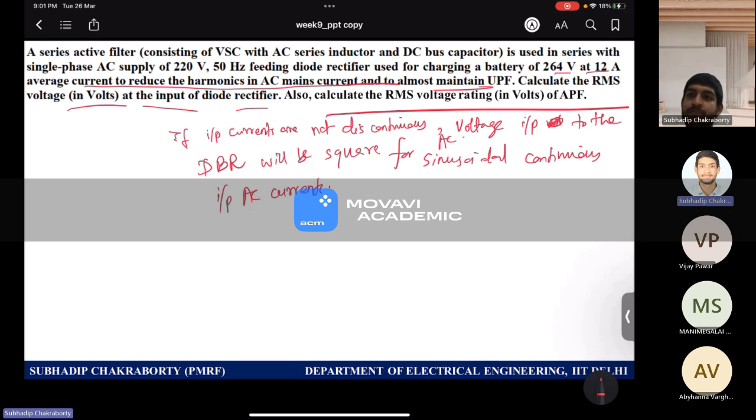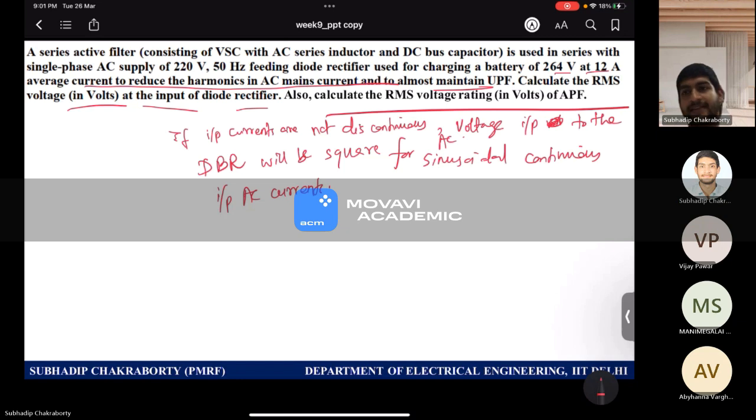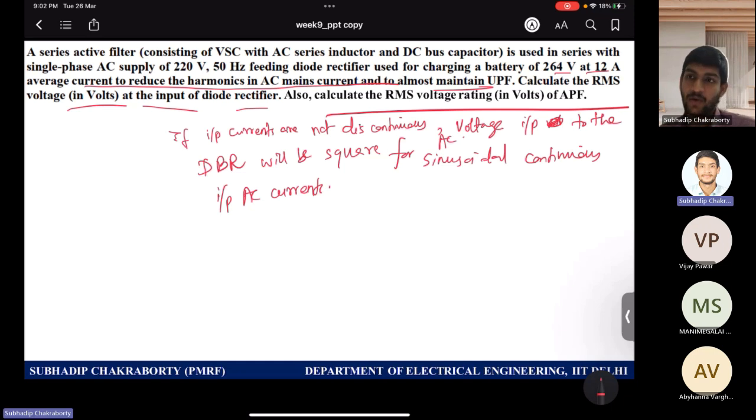That means you are continuously pushing currents. So the battery with a small r will behave like a voltage fed load, and it will toggle the voltage at every 180-degree conduction cycle. It will toggle the voltage, and the voltage will be square. So the current will be sinusoidal, but the voltage will be a square wave for allowing continuous conduction of currents throughout the cycle.